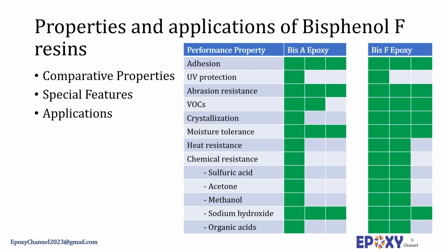The liquid Bisphenol-F resins have low viscosity, so they excel in workability and moldability, which makes them suitable to be used in many applications. These types of epoxy resins can cure at room temperature and also under heat conditions. The viscosity of the liquid Bisphenol-F epoxy resin is in the range of 4,000 to 6,000 millipascal seconds, almost 1/3 of Bisphenol A resins, and the EEW is around 165.